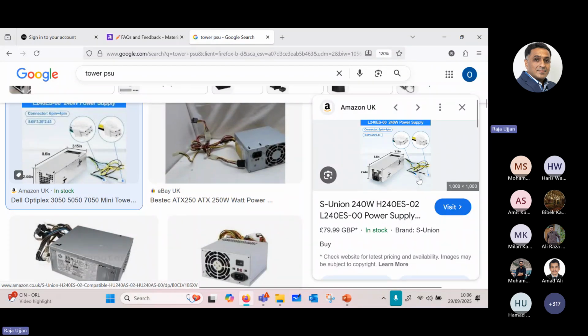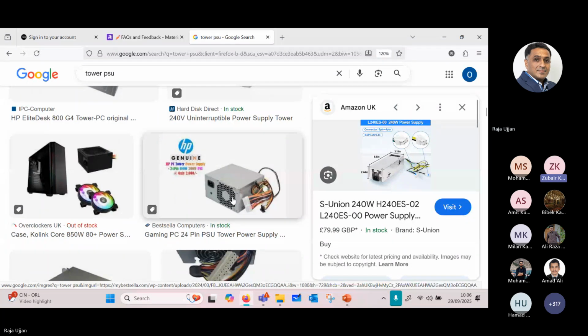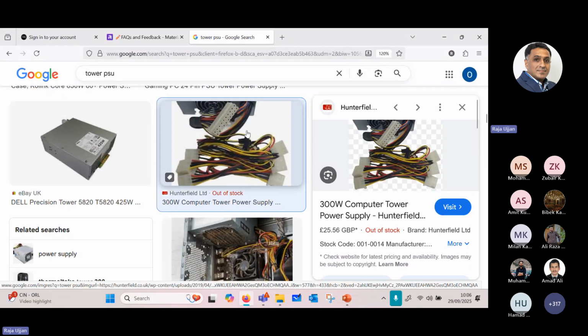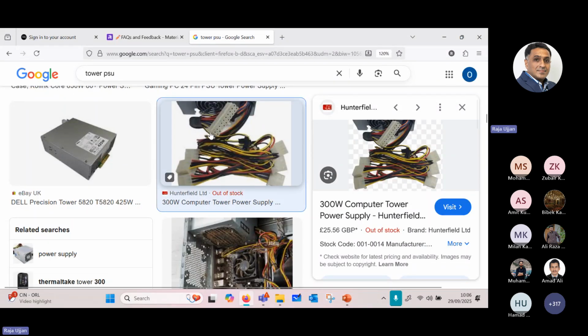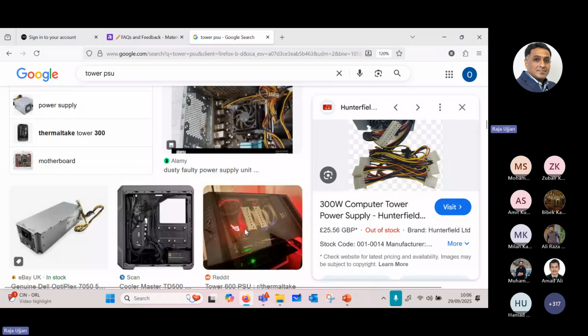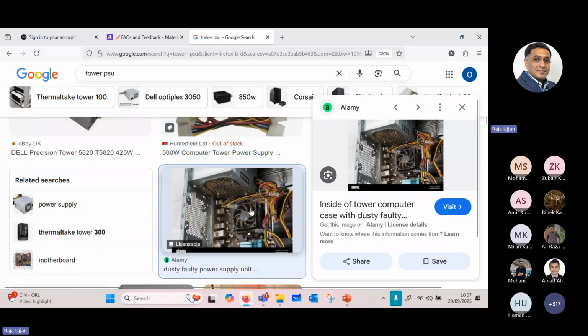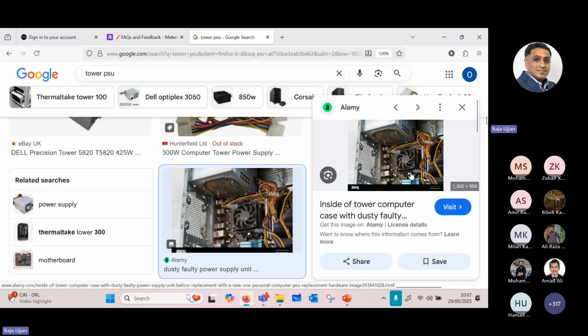Sometimes you use these cables for the graphics unit. Sometimes you use this port for your RAID driver. You use the bigger one for the motherboard, the smaller one for the RAID driver. They are different, sometimes 12 volts or 18.5. Yes, perfect. If you check your motherboard power supply, the maximum range is plus 12, minus 5, but there are some cables, yellow, orange, green, that are different. They use plus 5, minus 5, 3.3, something like that. Why? Because the motherboard has lots of parts, so some parts use 2 volts, some parts use 12 volts.